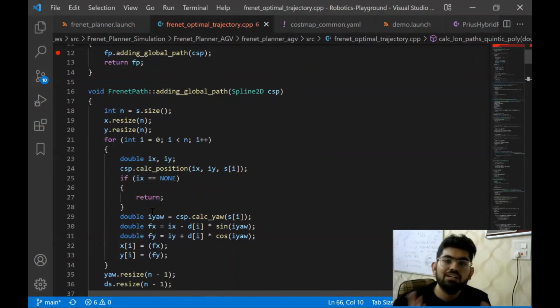Since robots do not have big computers that are present on their system, they have a very small computer with a limited compute power. Hence, the algorithm made for those computers should be optimal in terms of memory and time. The constraint is not only on the compute, but also on the physical environment. If the robot is not able to perform all the calculations in time, it would eventually crash into an obstacle. This Frenet frame method over here is quite optimal and can be made to run fast by using certain optimizations and parallelizations. All right, so this is it that we had to discuss for this video.